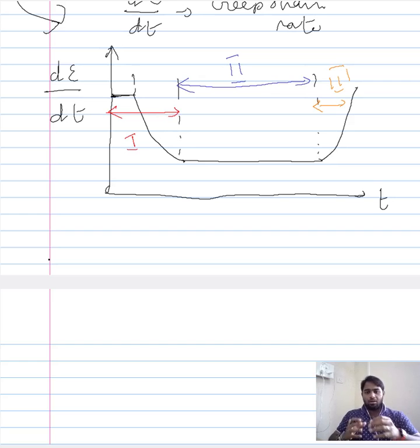Now, what we have in the x-axis of this creep curve is the time. Given that creep is defined as the time dependent behavior of the material, what we have considered in the x-axis is time, and this is rather accurate because over the period of time during the material response to the given conditions, there is a significant change in the rate of the response of the material, the rate of the strain that the material exhibits, and that is what we have shown here, and that is what helps us to section the overall creep curve.